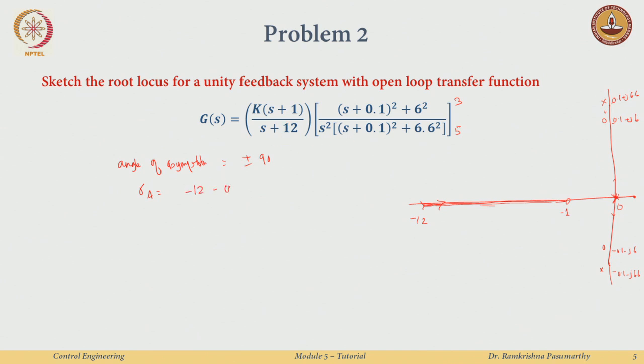I have a minus, again I just take all the real parts, if you remember how we derived these things, minus the 0 here, which is -1, and then the real parts of the poles, 0.1 minus 0.1, everything divided by n minus m, that is 5 minus 3, and this will give me a centroid point of -11 by 2. Okay, so somewhere here.